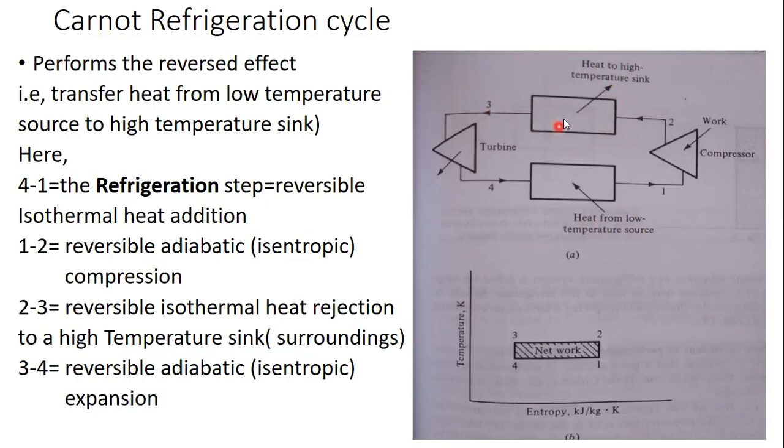But it will be at a higher pressure now, because when we are doing work by means of a compressor, the working fluid will be at a very highly pressurized stage. At this pressure, if we admit our working fluid directly to our freezer compartment, there may be a chance that the freezer compartment or the side walls of the freezer compartment may burst.